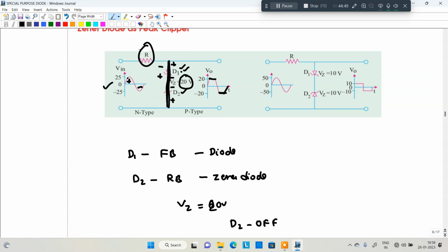Next, coming to here, this particular circuit is connected with two Zener diodes, here 50 volt, here 10 volt. In that case, whenever it reaches 10 volt, up to that the Zener diode is open circuited. What about the voltage 10 volt present here? Once you reach 10 volt, the normal diode is conducting, the Zener diode is also conducting, and it maintains 10 volt. So 10 volt constant.